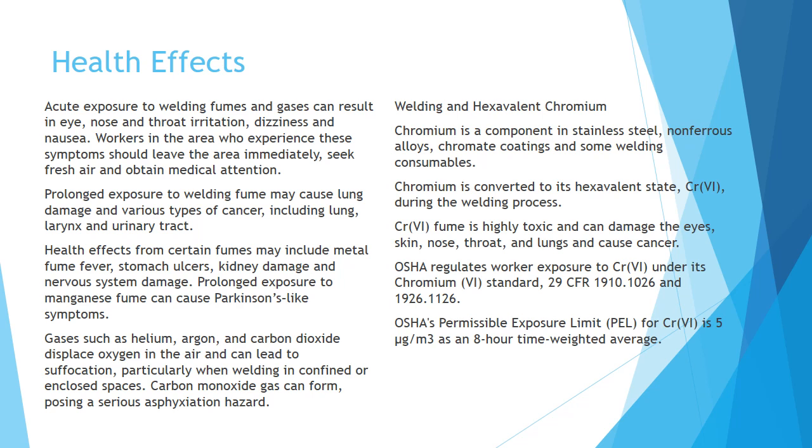Chromium is a component in stainless steel, non-ferrous alloys, chromate coatings, and some welding consumables. Chromium is converted to its hexavalent state, Cr(VI), during the welding process. Chromium fume is highly toxic and can damage the eyes, skin, nose, throat, and lungs, and can cause cancer.